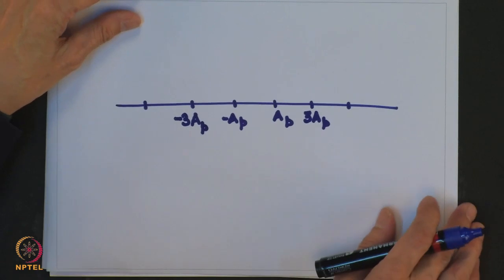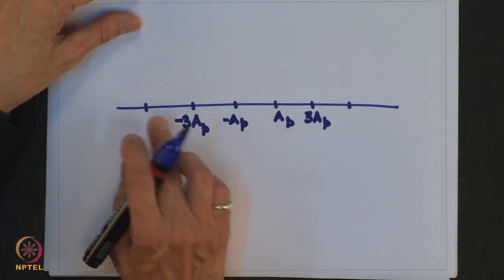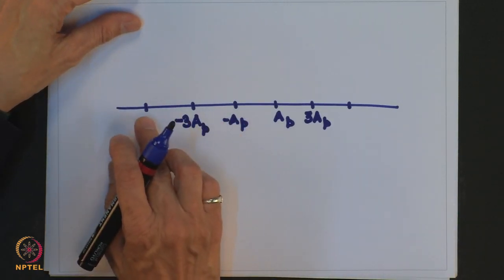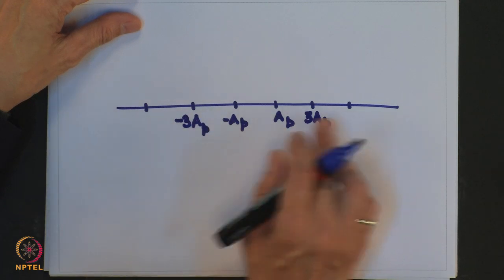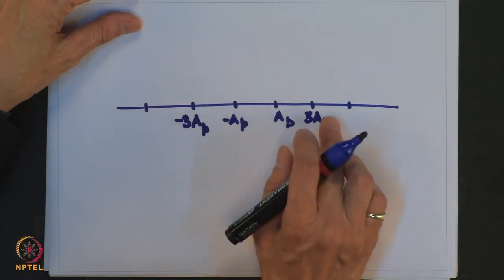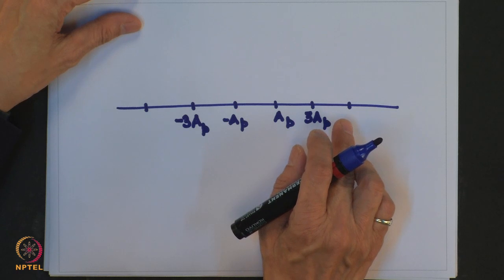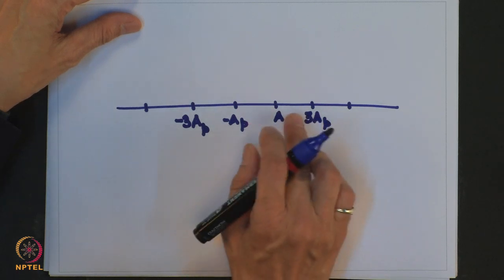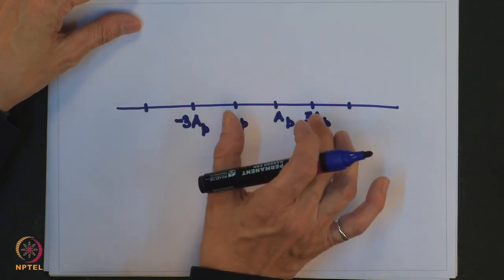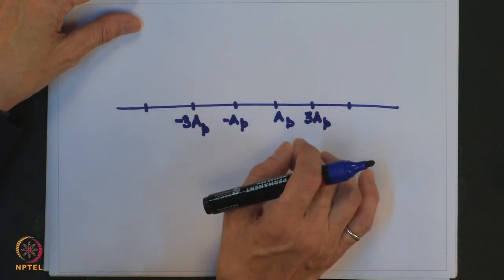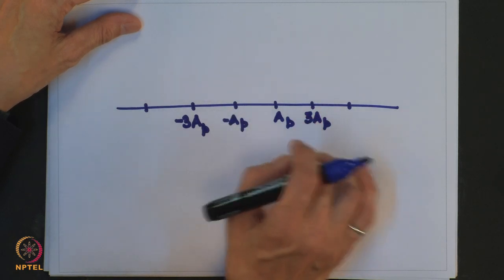So, the signal constellation is nothing but the representation of the message signal in the orthonormal basis signal, which in this case is nothing but the pulse itself, Pt, divided by the root of its energy.